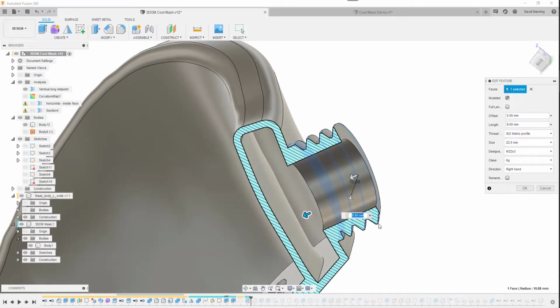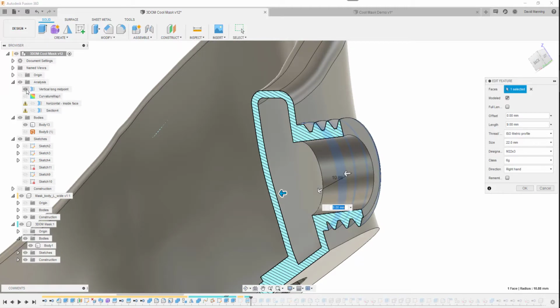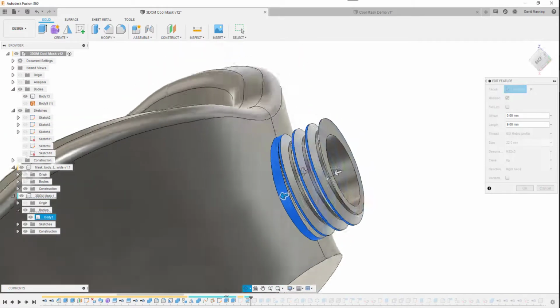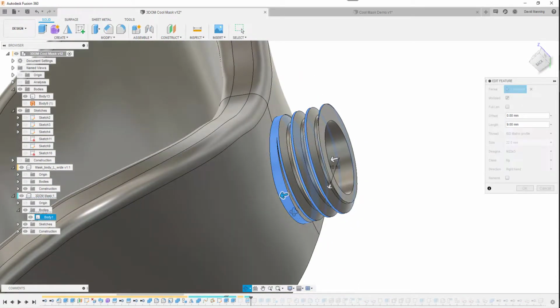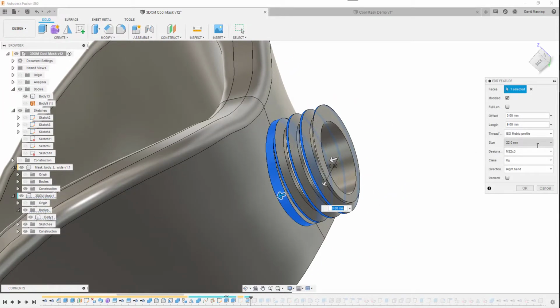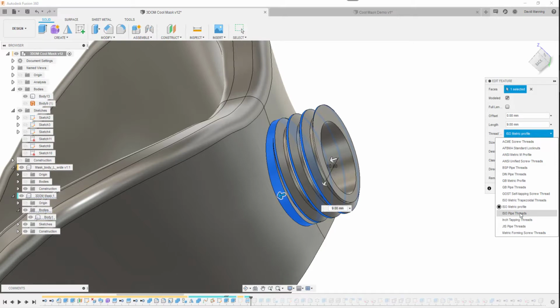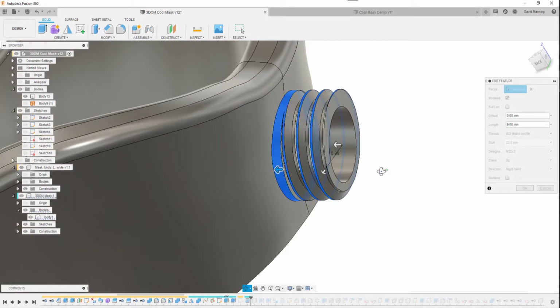That allows me to define a length for the thread itself that doesn't go the full length of the cylinder. So let's take that analysis off, and you can see there I have selected a random point which is 9mm, giving me a good bit of meat here for the join. That'll become important a bit later on, but 9mm should be heaps of thread. It's 22mm, and I've picked the largest thread I could because with 3D printing, that makes it a bit easier. I happen to find that it works well with the ISO metric. You can do ISO imperial as well, or the ISO pipe threads. It works for me, it works on the printers I typically use. And so that creates the thread, really nice and easy.